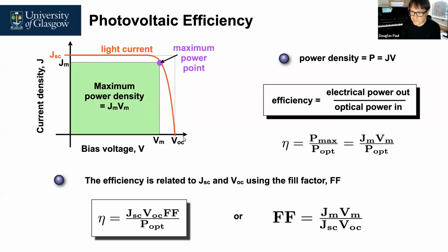So to compare all photovoltaics, you take the short circuit current density, you take the open circuit voltage, and you define a standard circuit that gives you the maximum power output for a particular impedance. This defines what's known as the fill factor, which is the difference between, if you like, this point and this point. So this really is a practical way of allowing comparison between all photovoltaic cells.